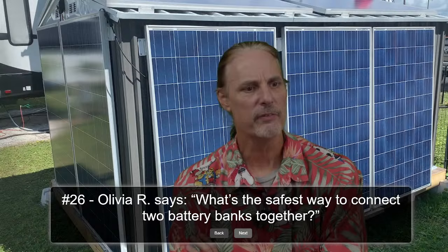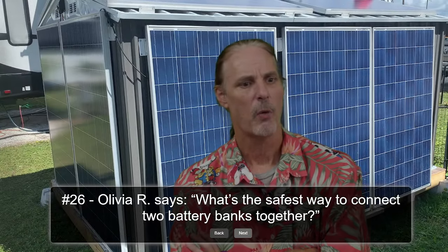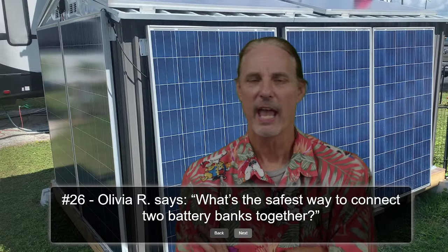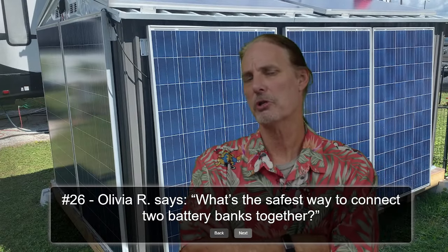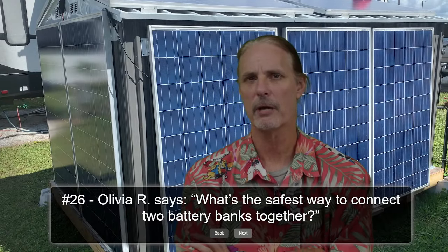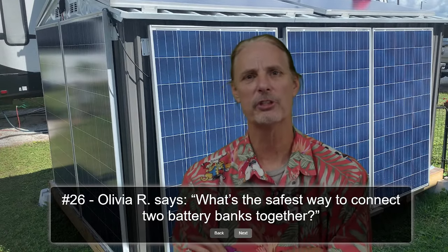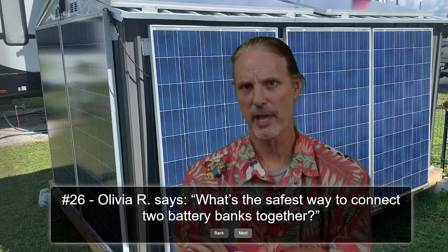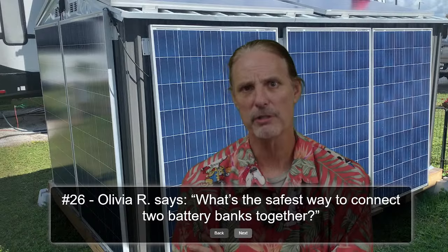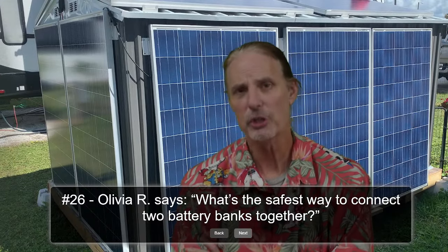All right, so Olivia R says, what is the safest way to connect 2 battery banks together? We've really gone over this question, but because it's specifically asked, I'll go over it one more time: bring them to the same voltage. If the safest way for you to do that, because you're not familiar with a meter or with measuring the voltage of the batteries, is to fully charge them all.